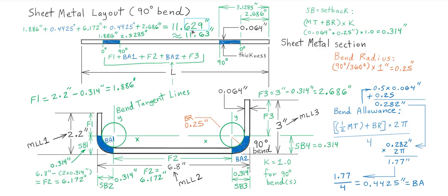So that's why you can just round this to 11.63 inches. And in aircraft structures, there's always a 0.03125 inch tolerance per side on any measurement. So that's 1/32 inch plus or minus on both sides. So if we take the totality of both sides on a cut, it would be 1/16. So you can actually round this to 11.6. That's what you would cut out, and you would make your cuts. So if you add up all of the side to side plus or minus 1/32 inch, it still comes in within tolerance.